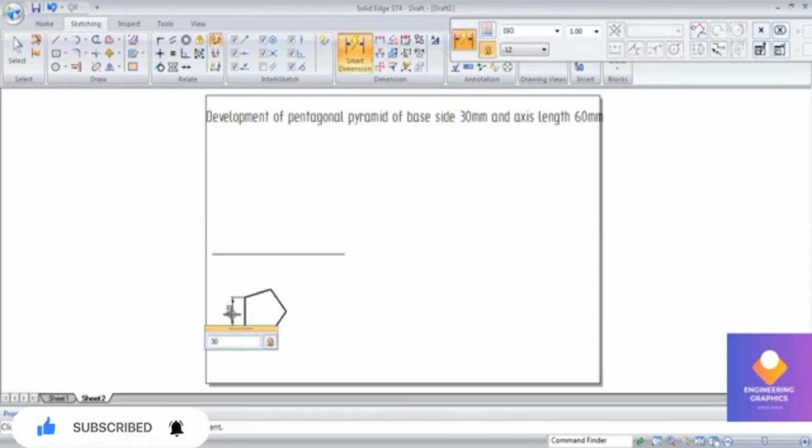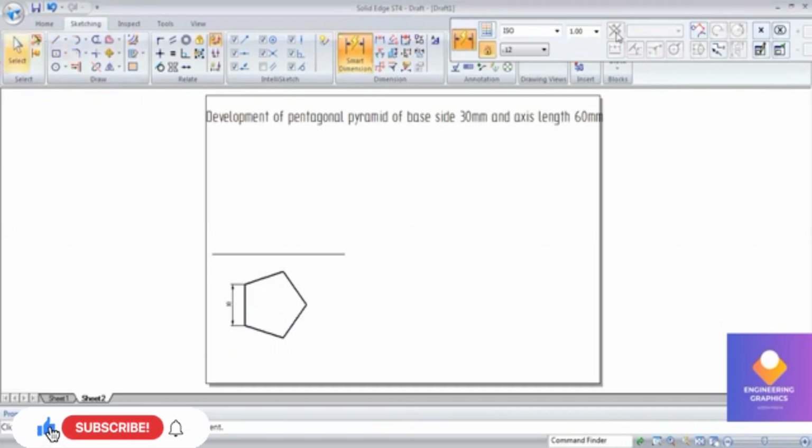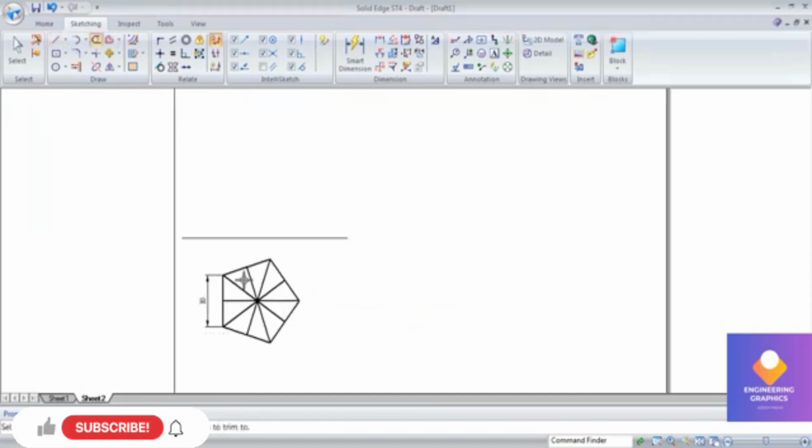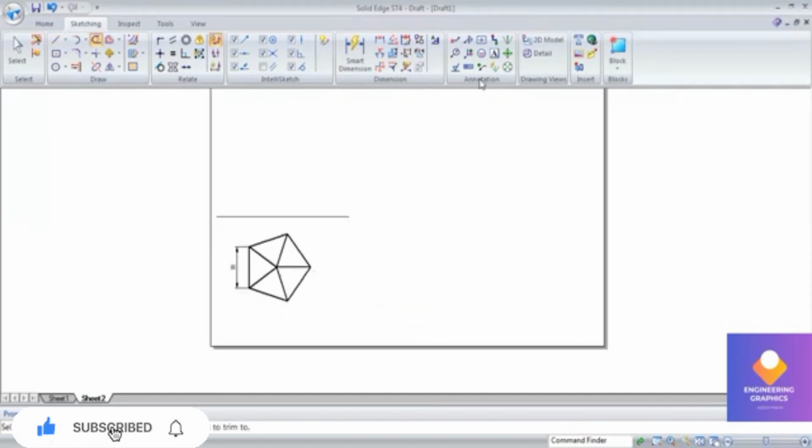Show the dimensions. Okay, so now it is a pentagonal pyramid, so we have to draw perpendicular bisectors here. Totally 5 perpendicular bisectors we have to construct. And then we have to retain only the slant edges which were coming from the corner. Using the trim command we will erase it.